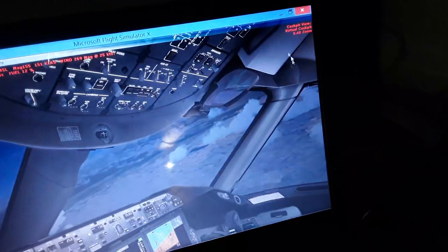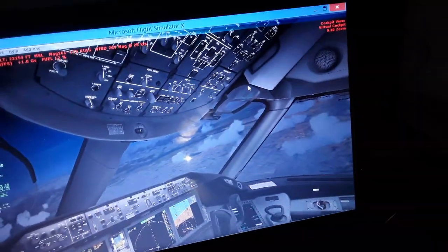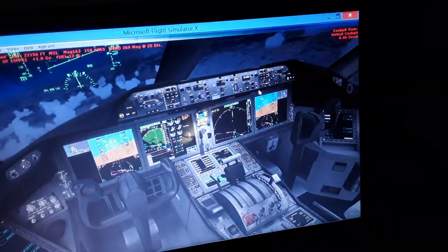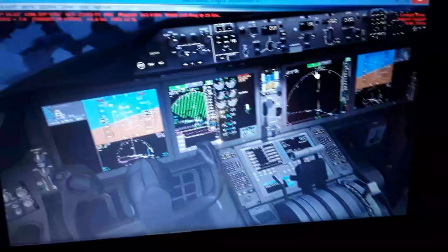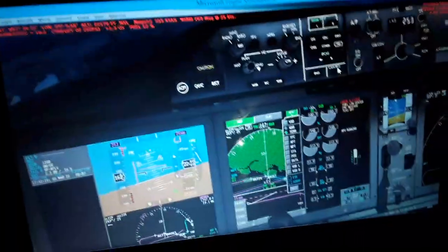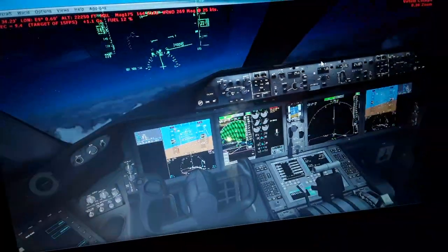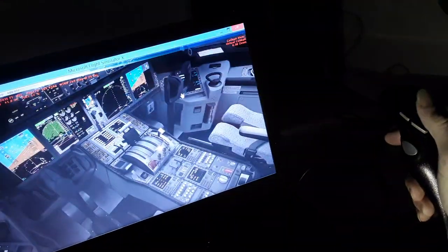So we need to use the pressurization at total position over here, about 30,000 feet. So we turn, we had a cabin altitude warning. So this is good, it's like the original aircraft. It should rectify now the cabin altitude because we set it to the auto.